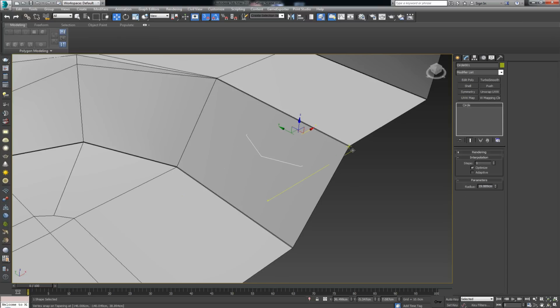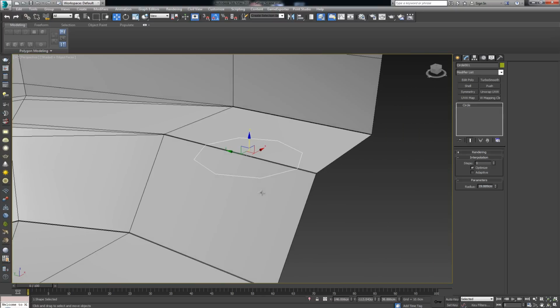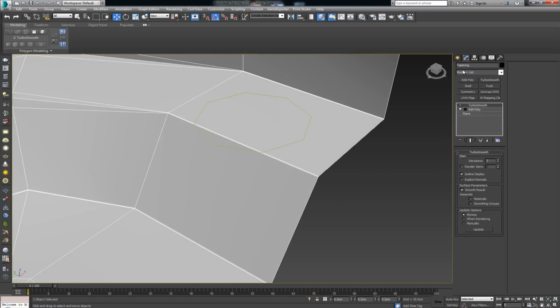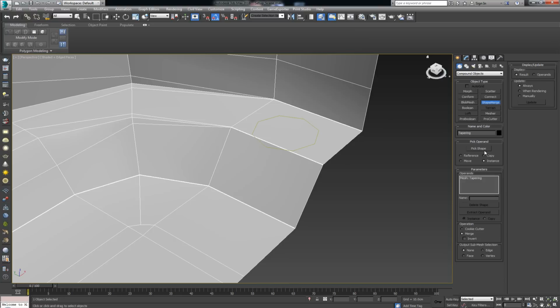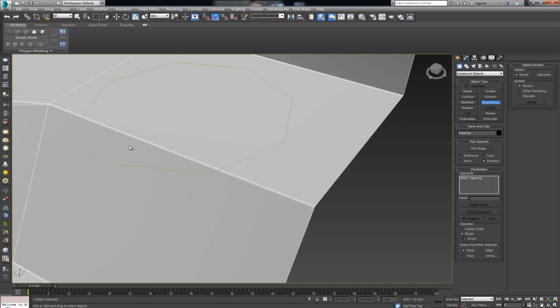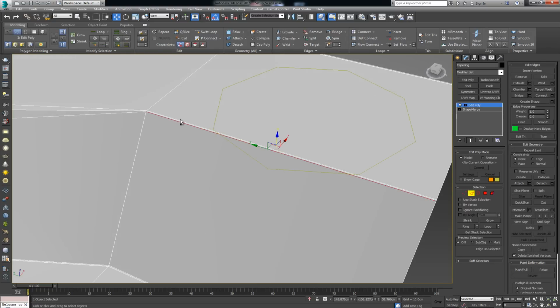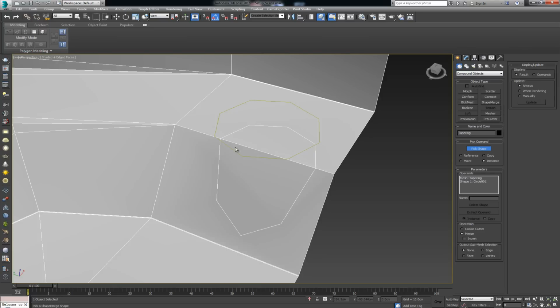Okay, I'm going to move it and position it like we did previously on the edge. So there we go. Let's see, it's the right one. Yes, it is. All right. I'm going to come down and delete this. Turbo Smooth. Come down and from the compound object, go Shape Merge, make a shape, and project it downwards. But before I do this, just so I make it easier on myself, I'm going to delete both of these edges. So Control Backspace, and now Shape Merge, pick a shape, and project it downwards here.